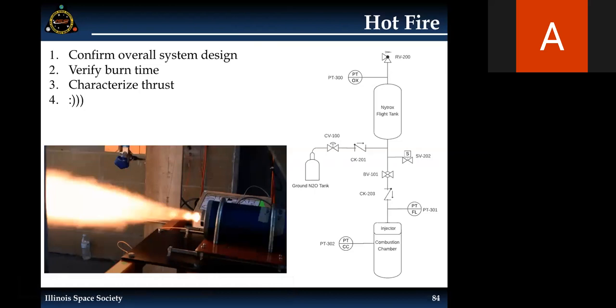And that's where we actually verify the burn time, so how long we'll actually be burning for and generating thrust, and characterize the amount of thrust we're producing, and if there's any weird thrust behavior due to any part of our construction. And this is also just going to be fun because we get to see hot gas come out of the rocket, and it'll be kind of vindicating that we got it to work.